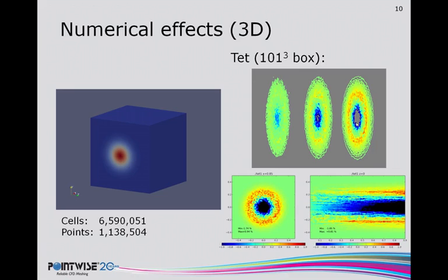The point of this is not to cast doubt on unstructured grids and unstructured solvers in general. In fact, many commercial codes contain more sophisticated algorithms that help mitigate these numerical errors on unstructured grids. Rather, the point is simply to highlight the tendency for tetrahedral grids towards numerical diffusion and to showcase a specific tailor-made example where the unstructured grid does not do an adequate job of resolving the sharp gradient. This is just kind of a best practice sort of approach.